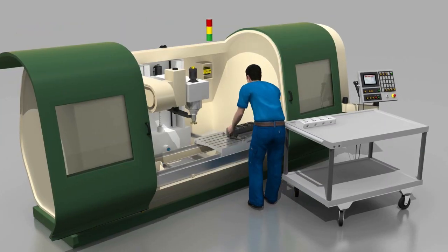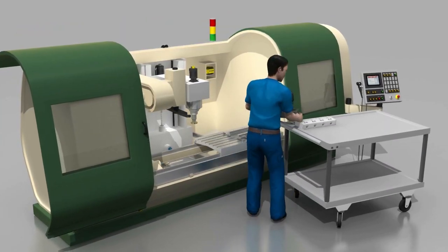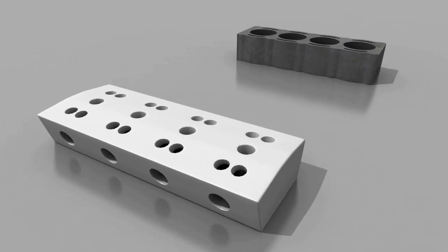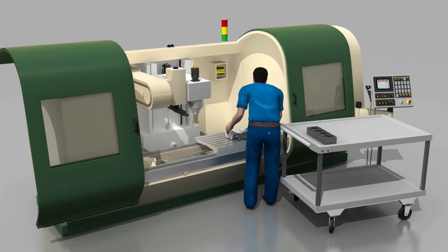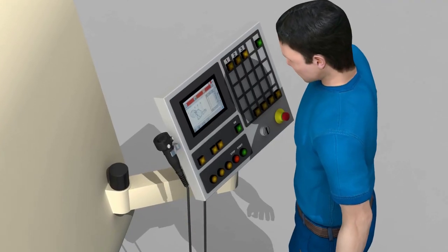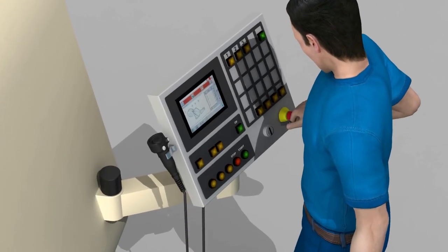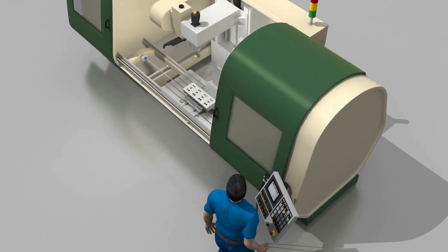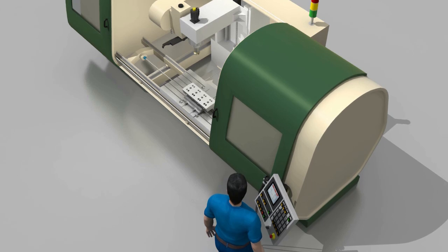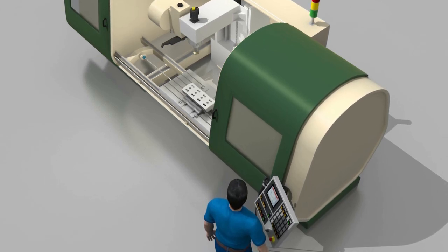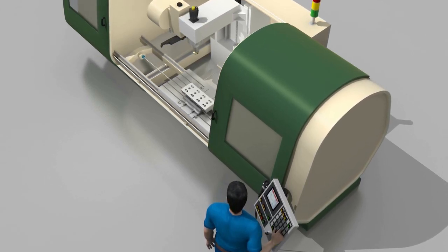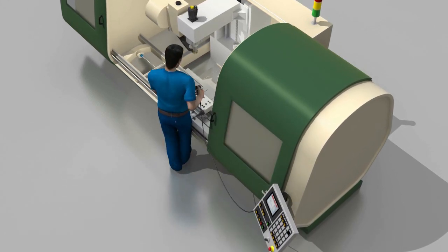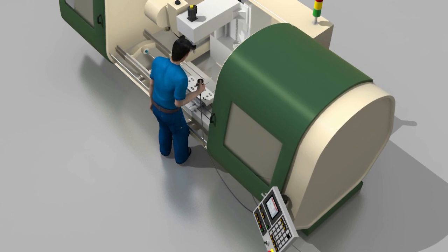The drive monitor is also the ideal choice whenever the machine needs to be set up for a new workpiece. To avoid damage to the machine and reduce changeover times, it is important that the machine is monitored. Once the operator has inserted the new workpiece, setup mode is activated to check the new production steps. The machine can then be set up with the aid of the enabling switch with the protective door open and the machine operating at a safely reduced speed.